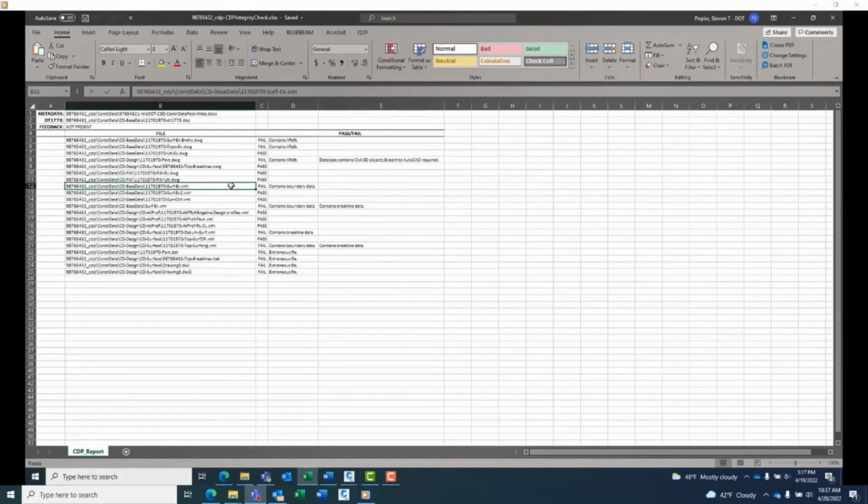So we do have a workflow documented on our Civil 3D knowledge base, and what that involves is opening a new file, data referencing in the design surface, and then exporting it to LandXML, which I did here in this version 2, and you can see that that message goes away. And it will also typically significantly reduce your existing surface file size.